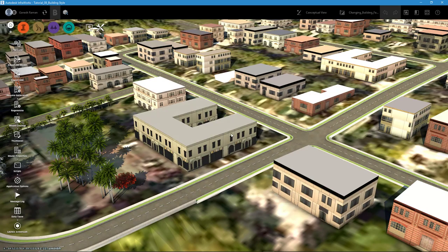So I'm going to hover. Nothing has changed. That is because it is very similar to if you have used AutoCAD before. When you do a lot of changes in AutoCAD, you have to regenerate the model. And since this is an Autodesk product, the same regeneration function is available here for the visualization of this three-dimensional texture mapping to show up in high resolution. So in the same Settings tab under this main flyout, we have Regenerate.